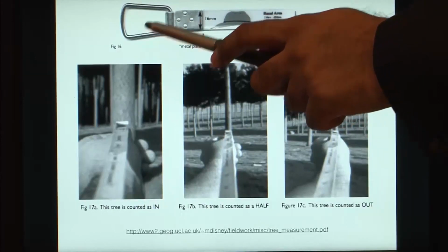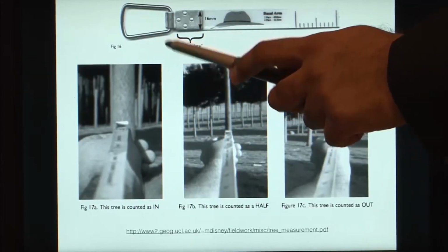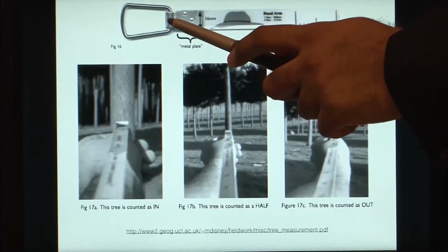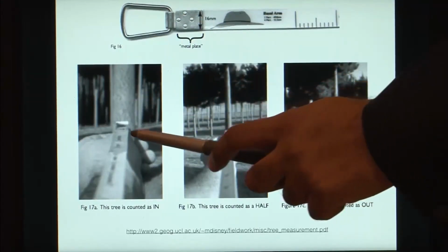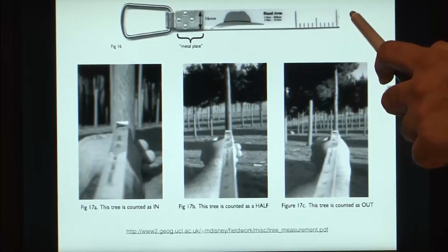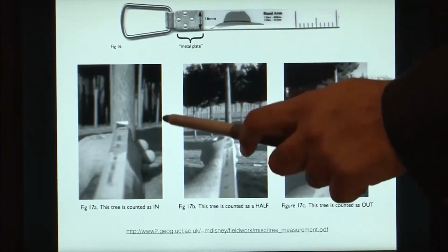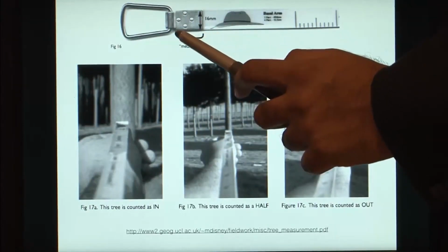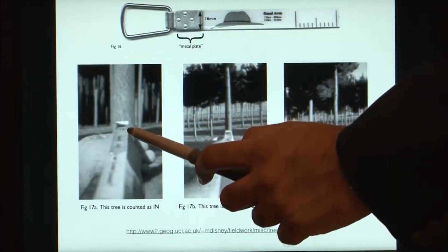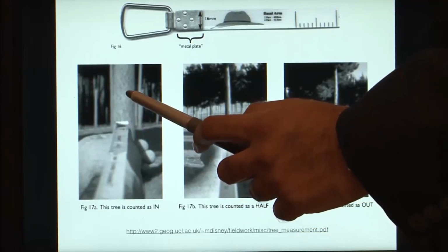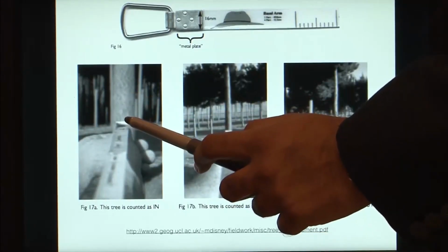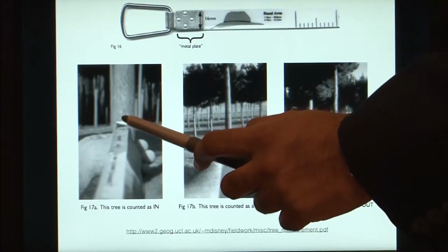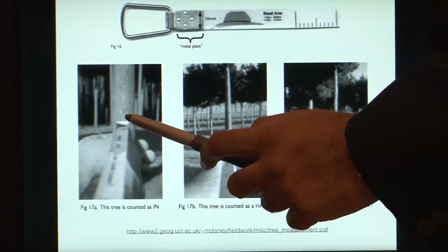So, now if you take this hook-like portion downwards, then this metal strip can be used to measure your trees. For instance, you are keeping your eyes somewhere here and this point is downwards. You are holding it in your hands and looking at this top portion. This top portion is subtending an angle, and in this case the tree is subtending an angle that is greater than the critical angle, because the width of this tree is greater than the width of the top.